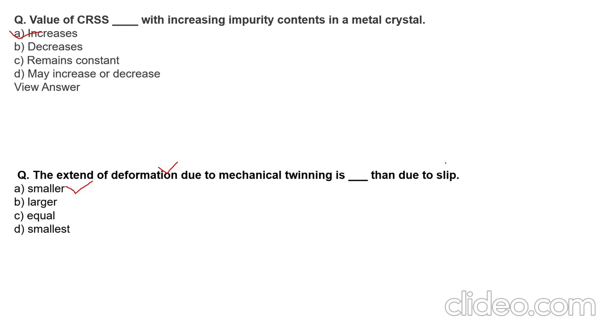So they have two different structures, and because of the difference in structure, their mechanical deformations will be different. There will be more chances of slip in an FCC structure, while there are more chances of twinning in an HCP structure. Because more slip can occur, more deformation is possible. So that will also influence the properties of the material. You should understand the crystal structure, the slip systems, and ultimately the effect of those slip systems and deformations on your mechanical and other properties.